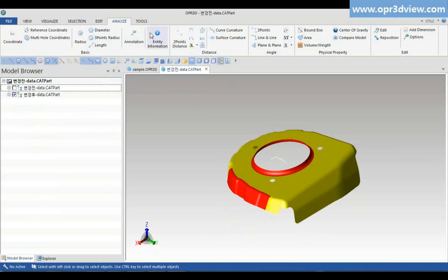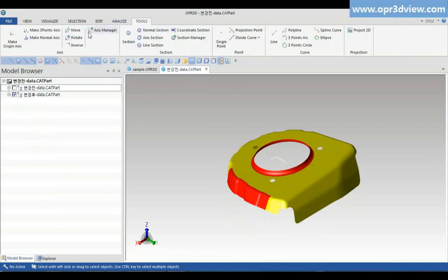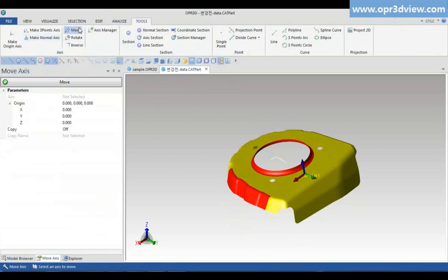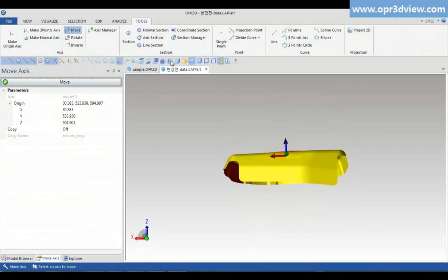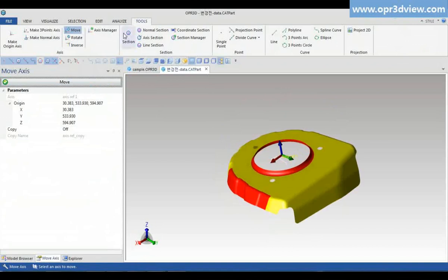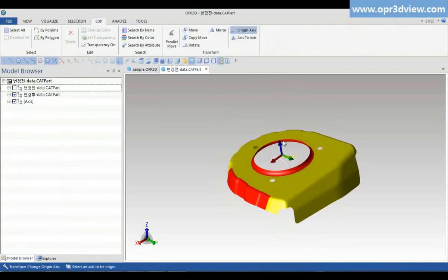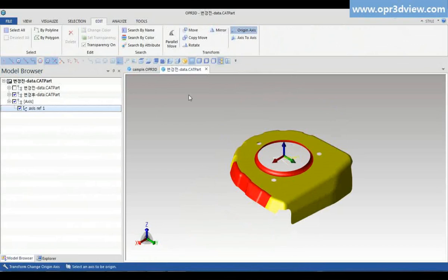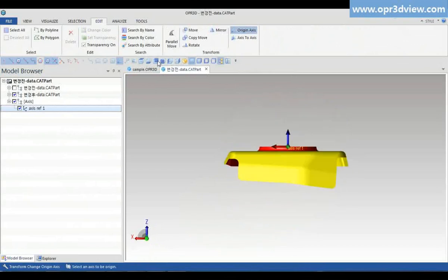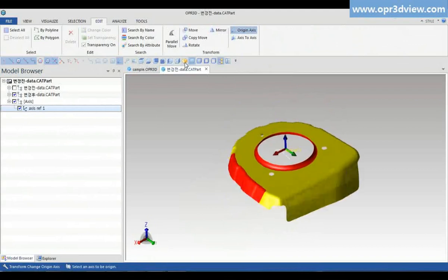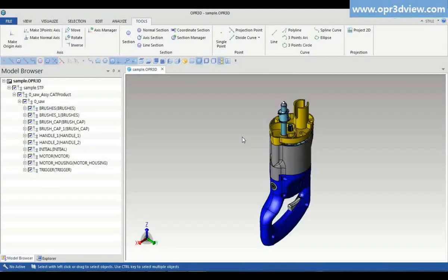The next step, I create a new axis and change the origin of the shape using the axis. Make a vertical axis of the plane, and move it. It is also possible to position any axis made. This setting can be made for a new origin easily, just select the axis that has been moved. Especially, it is possible to change the reference axis of a shape that is inclined to set a new direction of origin and shape.